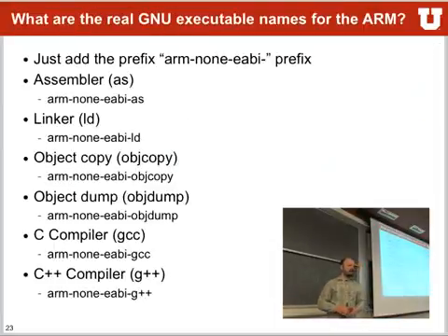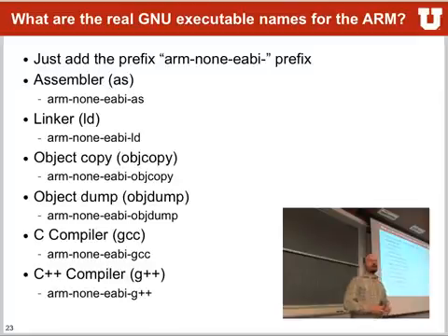There are a lot of different tools that you might already be familiar with from the GNU toolchain. The big difference is now, because we're using a cross-compiler toolchain, you're adding arm-none-eabi as a prefix to them. So if you have used GCC before, you now just use arm-none-eabi-gcc. If you used ld, the linker, before, you now use arm-none-eabi-ld, etc., etc. The key here is that these tools are cross-compiling. So they're taking code that you're writing on, for example, an x86 machine and compiling it for an ARM platform. In our case, this will be an ARM platform that's adherent to the EABI binary interface, which we will look at later on.